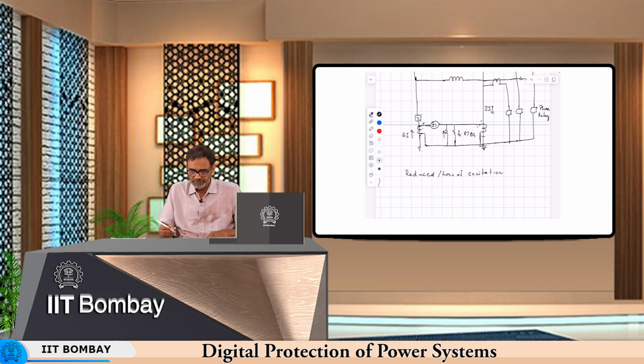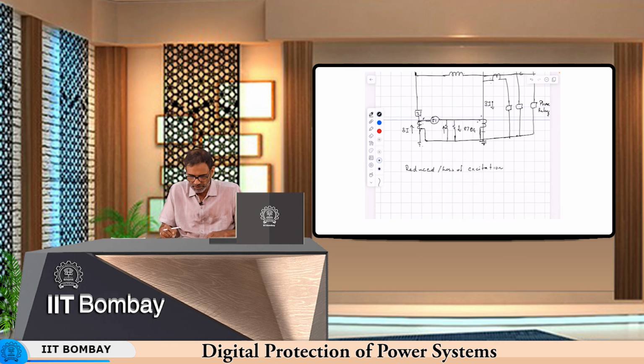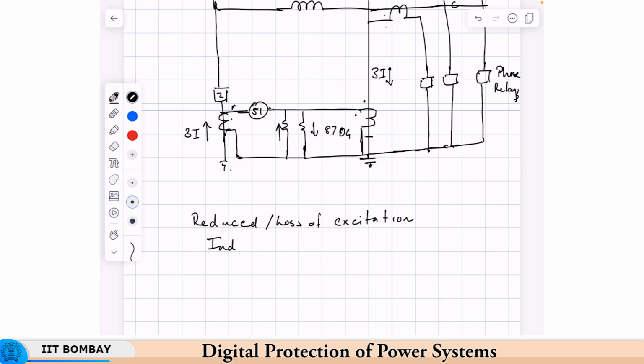Okay. Now, as we discussed in the beginning, a synchronous generator is a doubly excited machine in which you provide a DC excitation to the field. Now, if there is somehow a loss of, or even a complete loss of excitation, it would lead to operation like an induction generator.